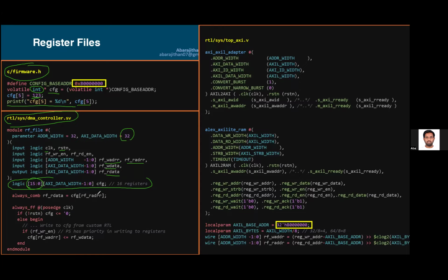Now what you do is you connect this combinationally to this. That is, R data is equal to RF of R address. So whenever you get an address, you get the data at that address. The reason we do this is because we are using this XLite RAM, to convert this, and that expects the data to be combinational. That's why we do this. And when you write into that, you have one clock latency.